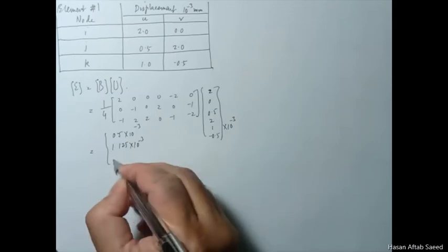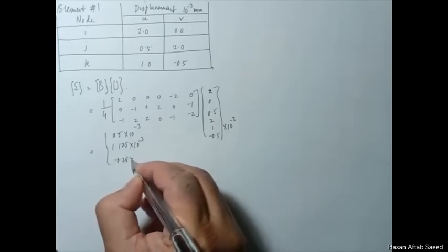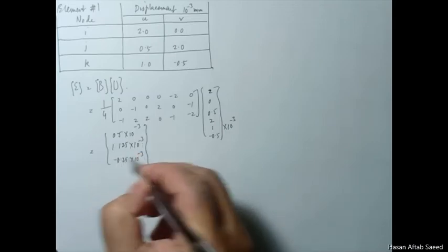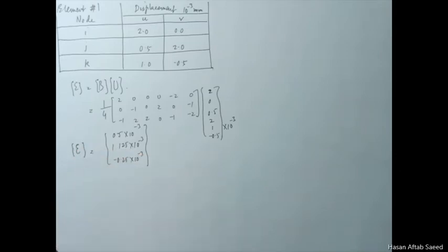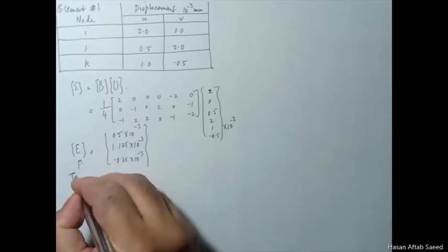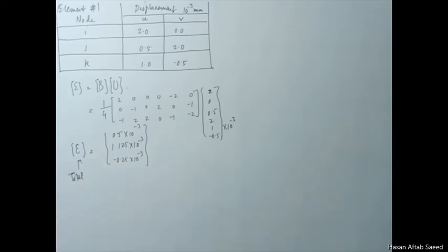the strain values. Now I am hoping that all of you understand that even if I write epsilon here, it means total, because recall that these u values have been arrived at after adding the temperature effects. So this gives us the total strain, not the mechanical strain. Now because we are going towards the calculation of stresses, we have to subtract those parts of the strains that are not mechanical in nature.